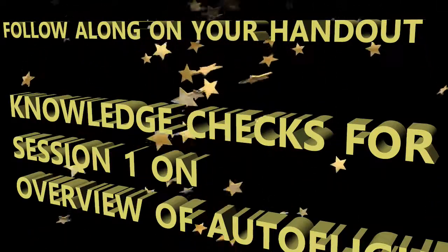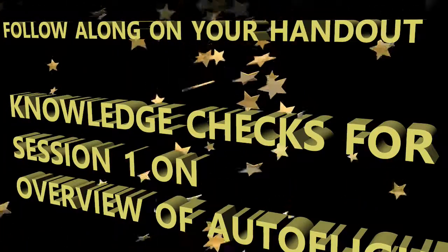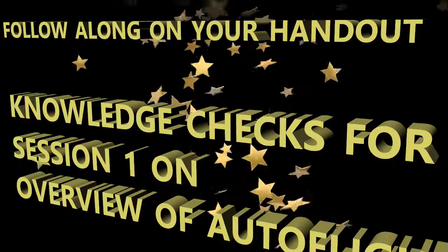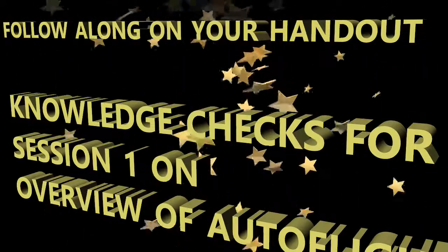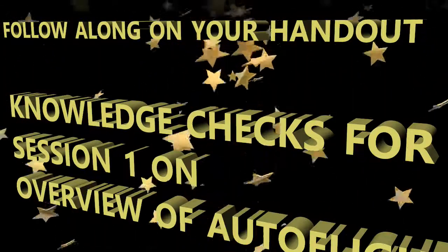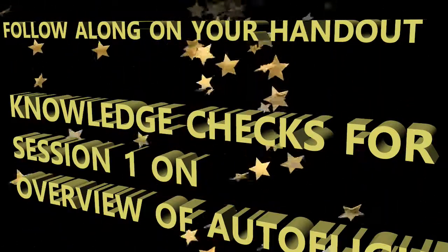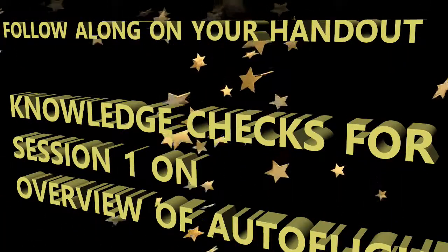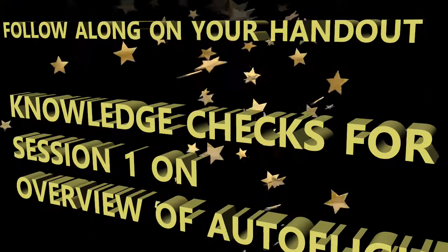Okay, I'm just going to pick and choose because there are a lot we could go over. Let's do one more question and then we'll call it. All right, so the autoland warning. I mentioned autoland very briefly, but there's an autoland warning that displays on the main instrument panel. Is that true or false? Okay, it's actually false. The autoland warning displays on the attention getter panel, which is on the glare shield panel. So that's where you'll see that.